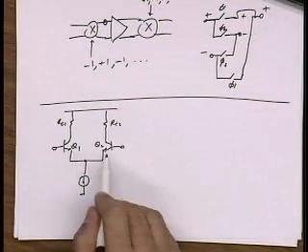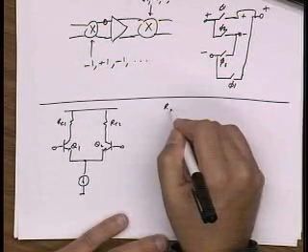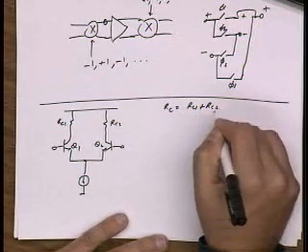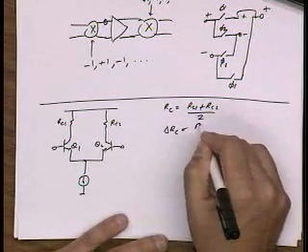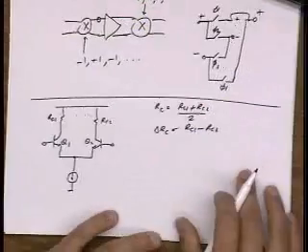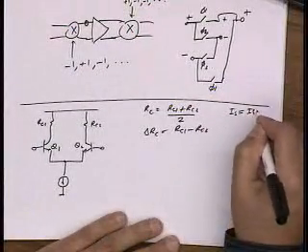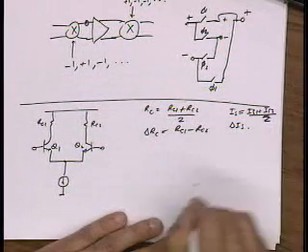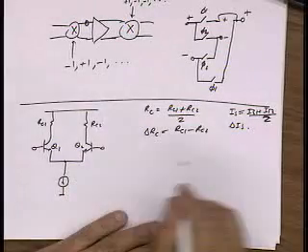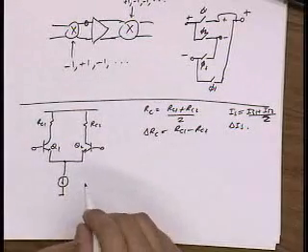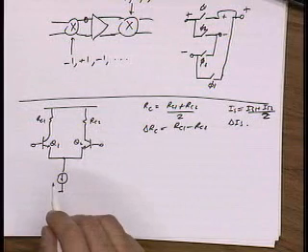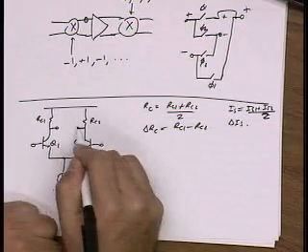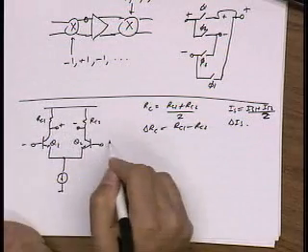So I'm going to define an average collector resistance, because they're supposed to be the same, right? And a difference collector resistance. And I can also define an average saturation current and a difference saturation current. And we did this before when we looked at matching and, let's say, resistors, so it's the very same concept. And what I'd like to do now is write an expression for the offset voltage. So here's the output. Here's the input.